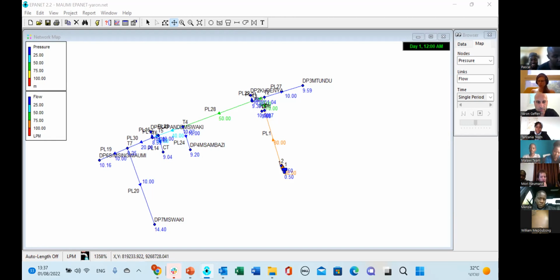Yeah, we are working per quarter. We are distributing water per quarter. That's why we have a different demand per tap. It's not something which is similar. And at the end of the day, the quarter where the population is higher than the other one, we will see that the diameters of the pipes are bigger because they need more water and more pressure.